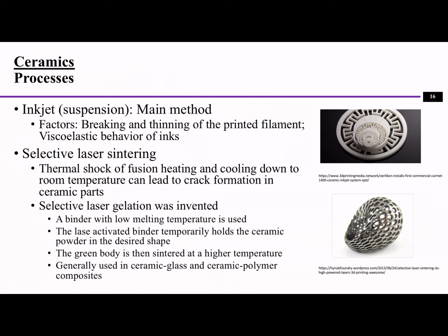So ceramics can also be used in selective laser sintering. But because ceramics have this kind of thermal shock behavior, when we are using high heat and then it cools down, or starts to solidify, it can lead to some crack formation in some of the parts. So that's one thing we have to be careful about during processing of ceramics in SLS.